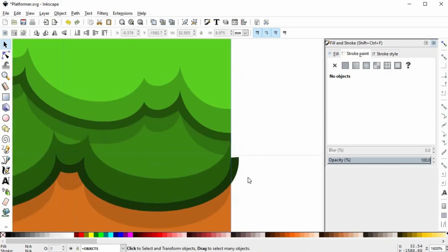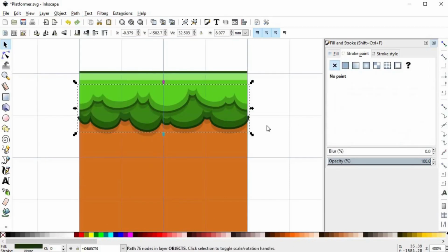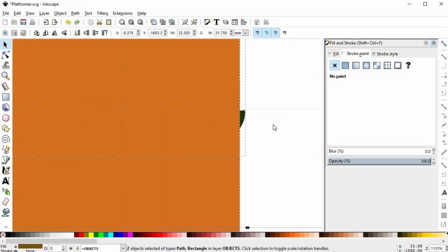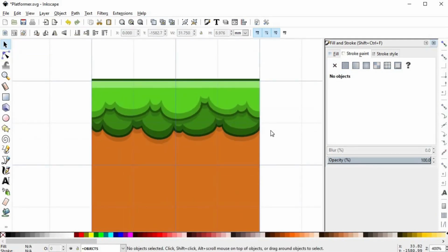It may happen that after you remove the side of an outline, a bit of the outline leaves the tile square. This is because of the way the outline is rotated. To fix this, there is no other way than to transform this outline to a path and intersect it inside using a rectangle the size of a tile. So make sure to give it the final shape and size you want before transforming it to a path, because once you do it, it'll be impossible to adjust anything.